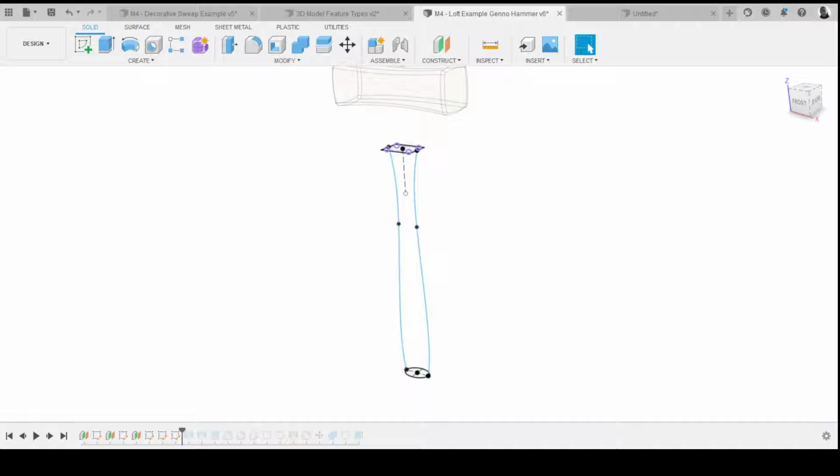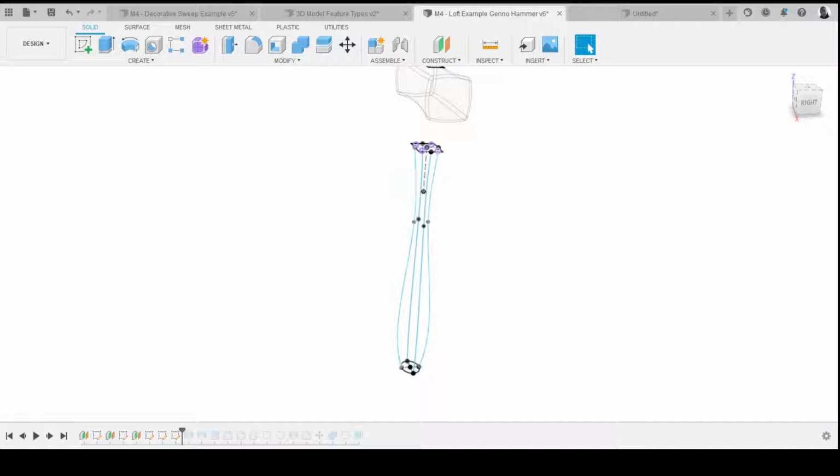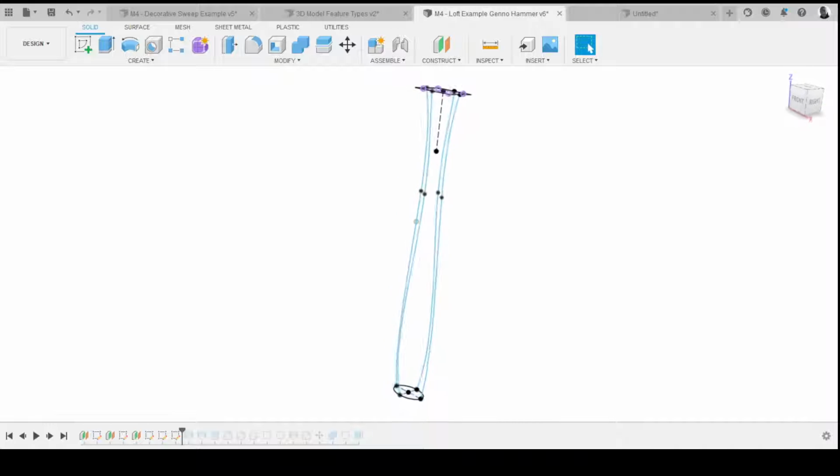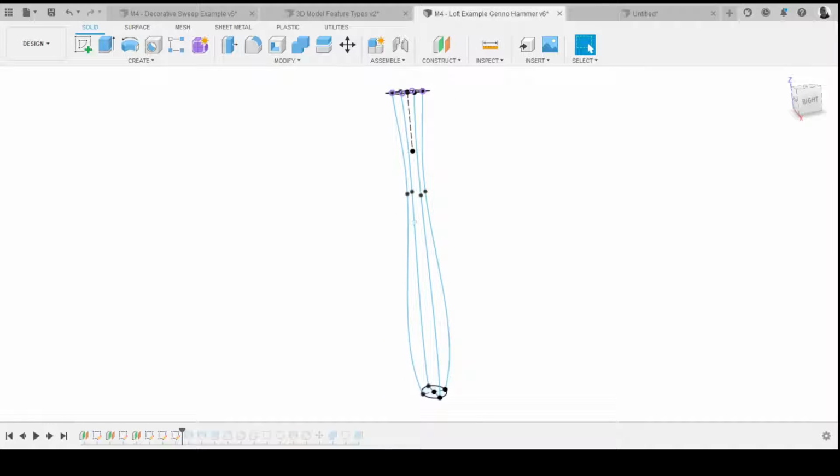So a spline like that, just a simple 3-point spline, which was then mirrored across to make it the same on the other side. Then I did exactly the same process this way round to create another spline coming from, this time, the other side of the rectangle down to the other side of the ellipse. Does that make sense? To create that, again, that wireframe. You're trying to give users as much information as possible to make that slightly more complex shape.